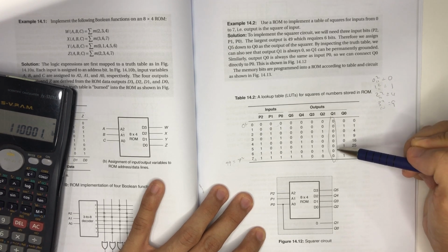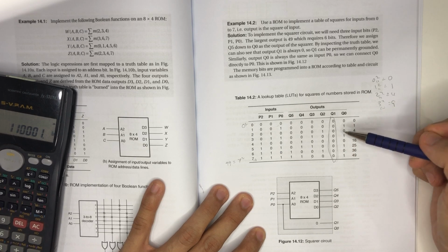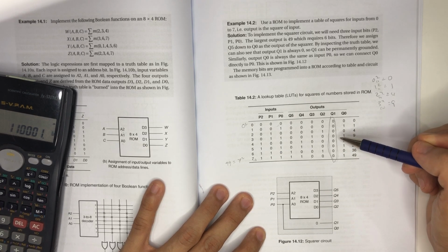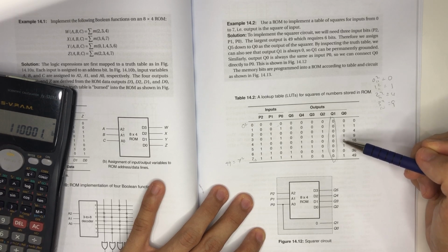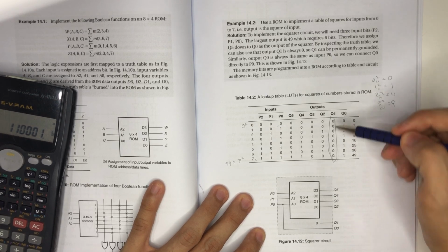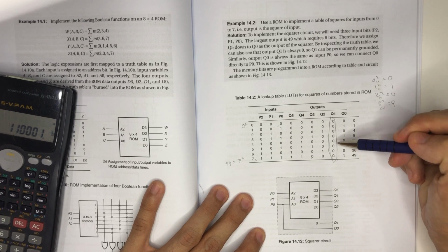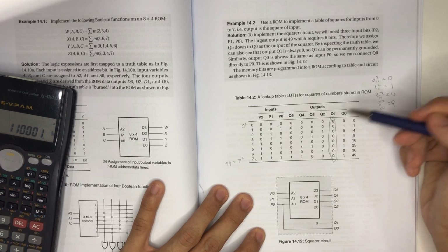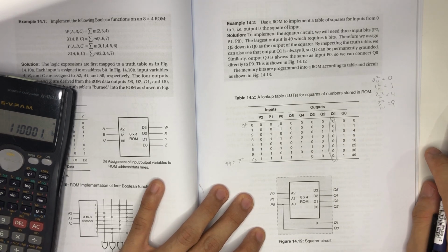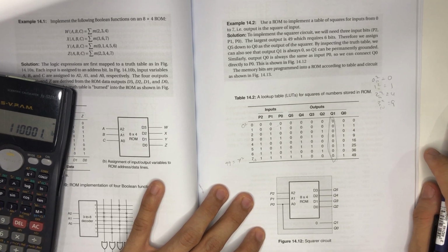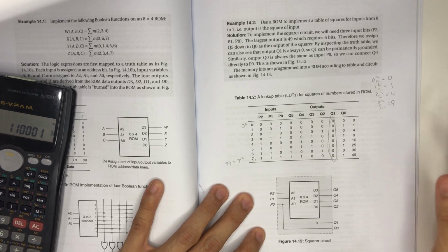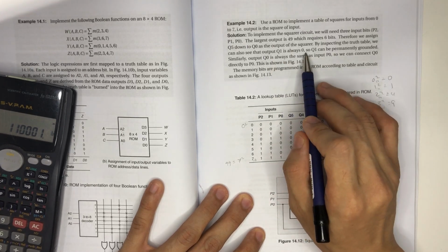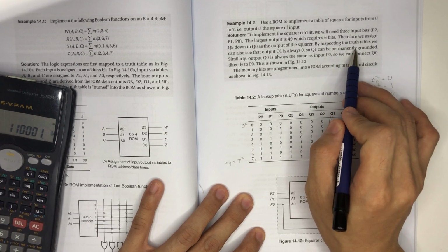This is very important for you to do the simplification, because it will be closely related to your design question. If it is always 0, you can connect it to the ground for your outputs, and if it is always 1, you can connect it to the source, for example VCC. So Q1 can be permanently grounded.